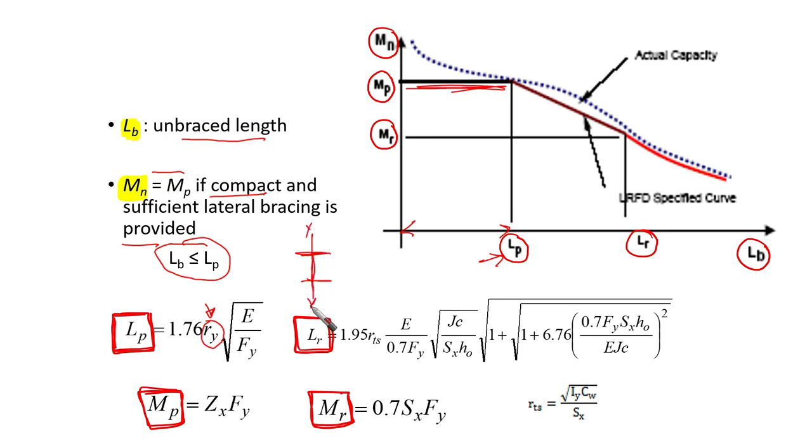If I ask you why we didn't use RX, because we are expecting what? Yes, lateral torsional buckling. So the behavior is going to be something like this. We are expecting the section to move laterally. So everything related to the least radius of gyration, around Y, is going to be there.